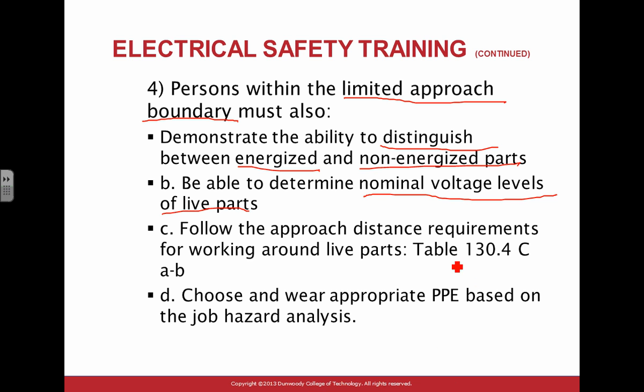And then of course there's the distance procedure, which you, my friend, have an activity for. You're going to be verifying the approach distance requirement for working live. If this is an open piece of equipment, how far can I get before I have to put all these things on me? So how far? Typically 3 feet, all the way 3 to 4 feet.